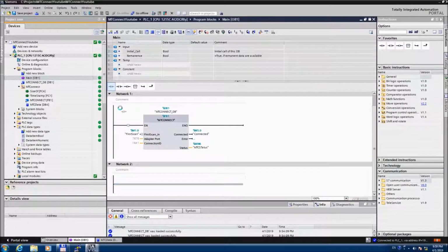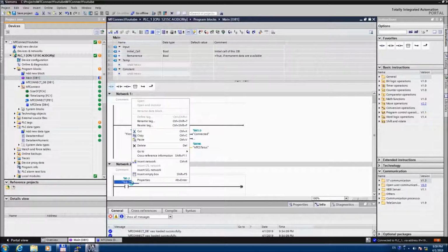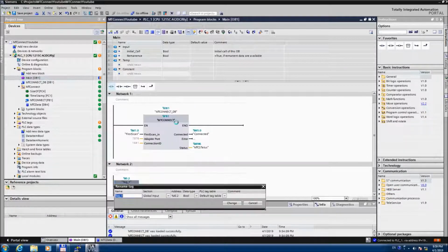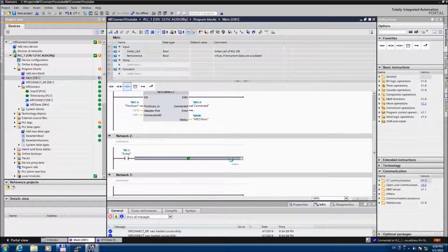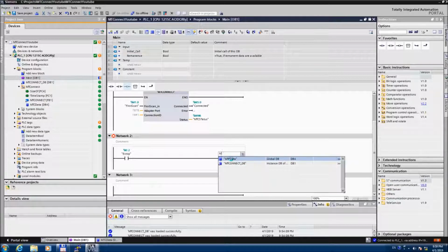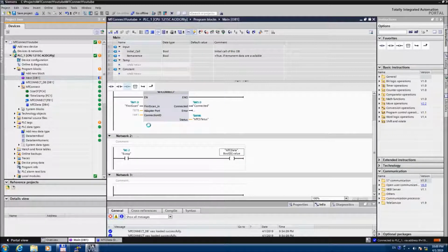I can show that here. So let's take a real world IO, I0.2, and let's rename that to the ESTOP coming into this machine. And then we will take that data, that Boolean, and put it into the structure for sending. MT data structure, Booleans, Boolean 0, and the value of that. So that will directly take that into the structure, and it will become available to the agent.